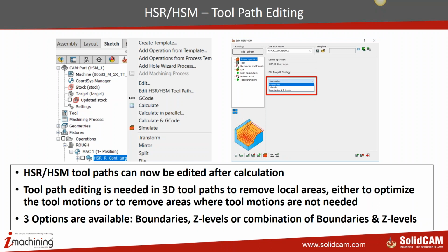In the service packs to follow and the new versions to follow, we will add 2 more functionalities of toolpath editing, and that would be editing using holders. You could have a finishing toolpath generated with a tool, and now you would like to split the toolpath based on different out-of-holder lengths of the toolpath. So you could keep trimming the toolpath based on the outside length of the tool from the holder.